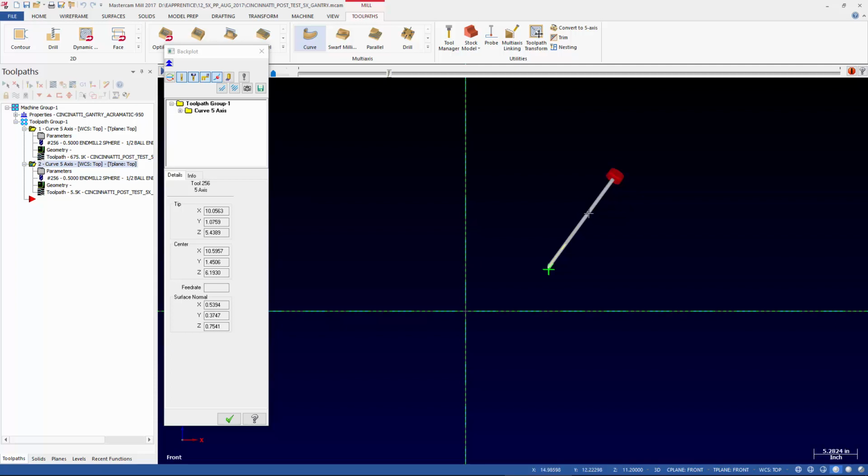The A-axis, or actually in our case, this is a B-axis spindle. So we're using a CB. B-axis is going to be pointing down here. And our tool, with our tool holder, is actually going to be somewhere around here. That's the only disadvantage of doing this style of describing the tool length: if we use the overall length of the tool, we don't get a realistic representation of the tool.